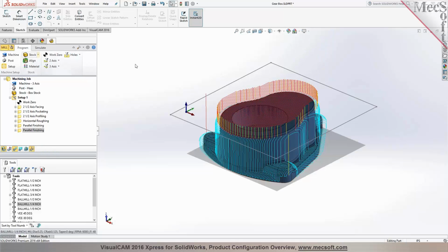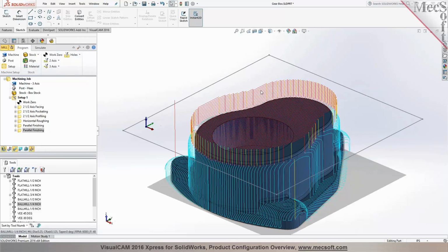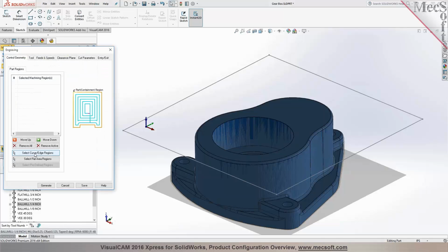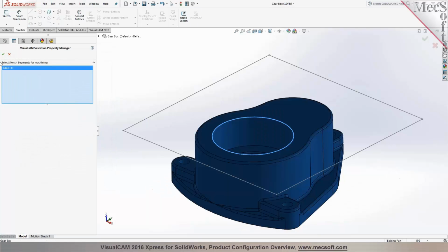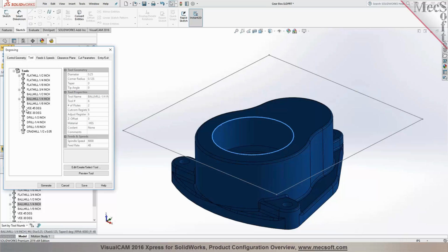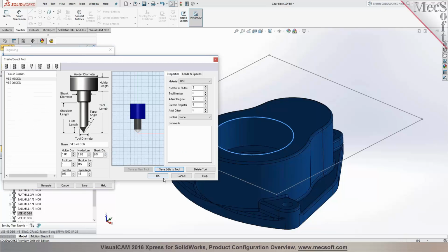And there it is. Now finally, you'd want to go ahead and chamfer this edge and then do a profile cutter on the part. So we'll go ahead and use 2-axis engraving, and we can use engraving to chamfer this edge in here with a tool. It could be like an engraving cutter like a V-mill or a chamfer bit. So the Express configuration allows you to select a V-mill for chamfering.